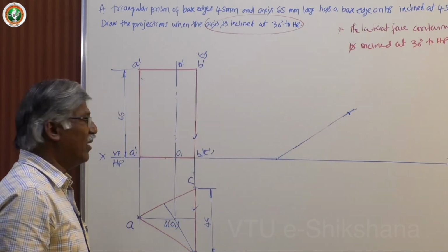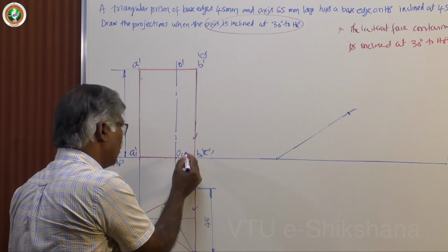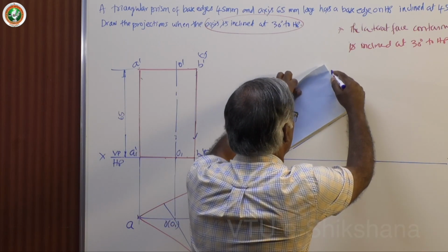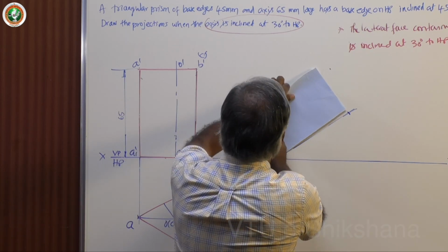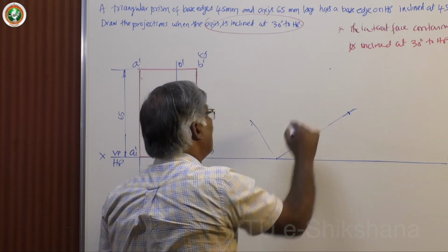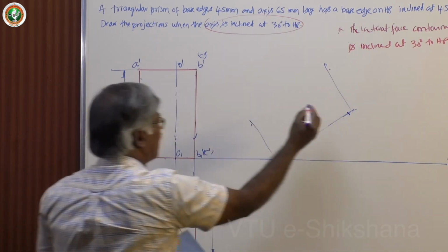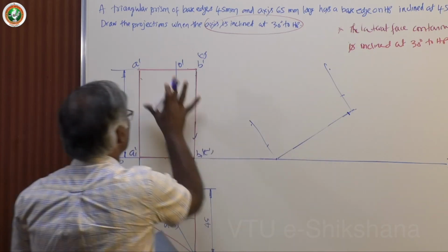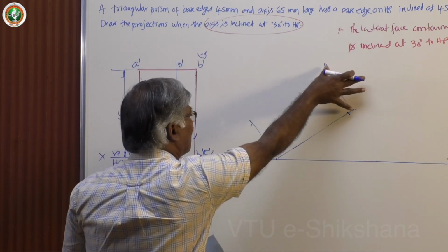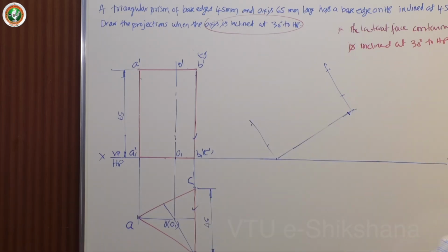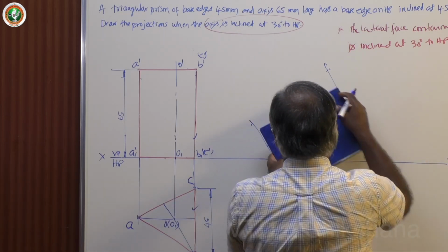How to redraw manually? Draw perpendiculars, because these two are mutually perpendicular. Draw perpendicular lines to that and try to take this distance. First, mark 2 points. The second distance is this. Mark 2 points. Then join them. Okay. Now we have the points ready.